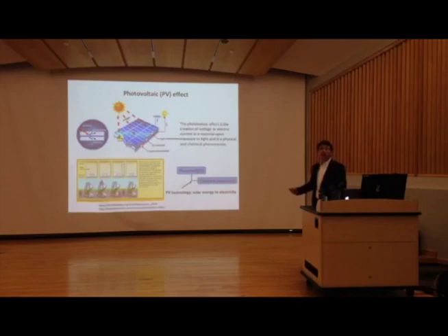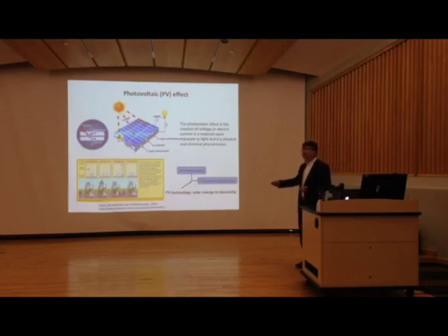So photovoltaic technology is a technology to convert light into electricity. A little bit about the technology itself. If you further zoom in on this area, you should be able to see this. The electrons inside this piece of material, the semiconductor, when they see the light, will jump to a higher energy state. So we say this electron gains high energy. And when it jumps to a high energy state, it leaves an empty space. We call it a hole, a positively charged particle. And when it goes through the external circuit, it goes back to its ground energy state. In this case, we generate electricity.